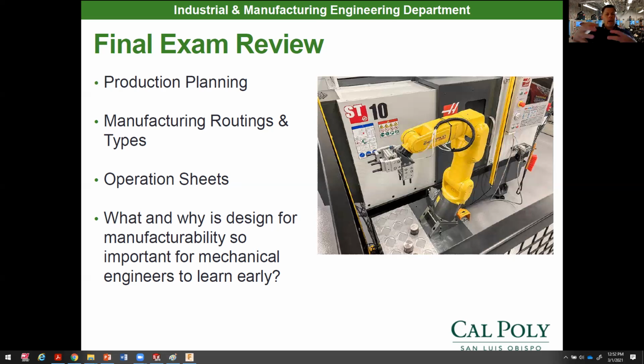Then we have operation sheets that tell me the specific instructions for one single operation. This is the instruction sheet for the technician to grab and basically set up an operation from scratch and perform a manufacturing operation. That makes it very repeatable for that technician to go over and do that operation over and over. So if they haven't run that job in 6 months, they get the op sheet back out, remind themselves, and fully set it up so it can run as intended.